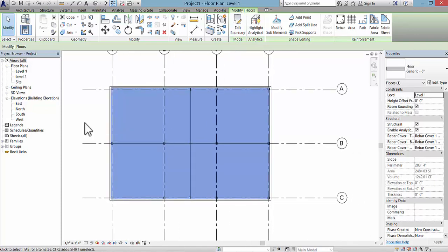When we look at the roof, we'll take a look at how to create indents so that it slopes, because this concrete slab wouldn't be flat. There would be places where it would drain. And so when we look at the roof, you can use the same concept here under the sub-elements and points to provide that kind of slope.